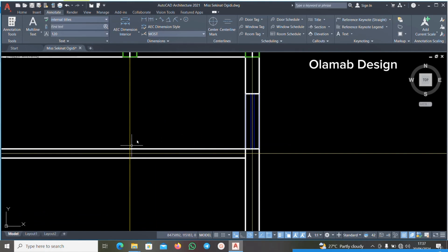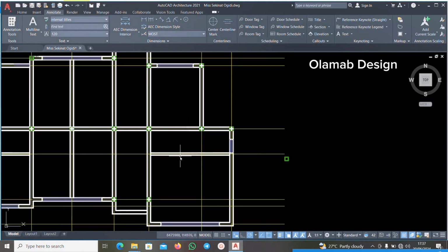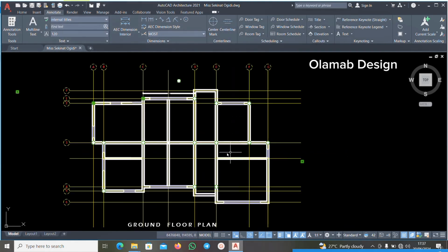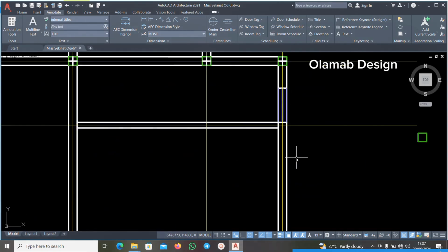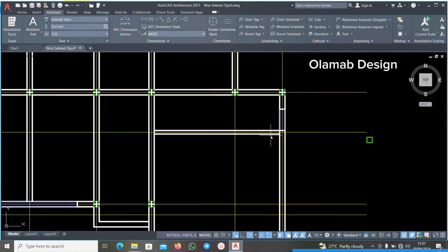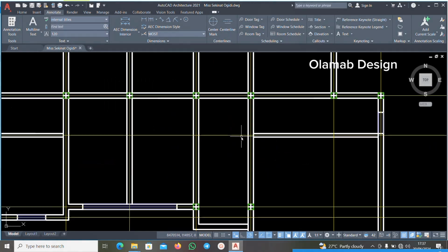This is a 150 by 225 mm wall, but because I just want to use that point for my beam, just to divide this panel, I don't mind that. And remember that my beam is going to project out, and because of the height of the building, it is going to be inside the ceiling. So I don't really have any issue with that.